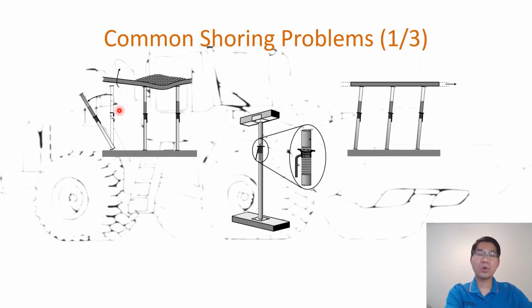Something that we often do not look at when designing the shore is that we only focus on the concrete load, the workers, and the live load on it, but not the wind, etc.